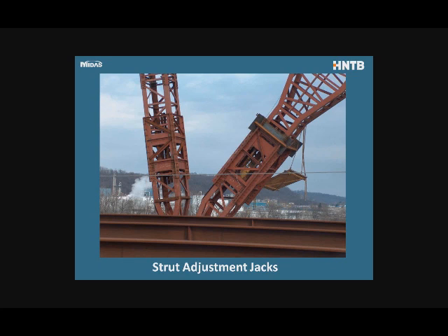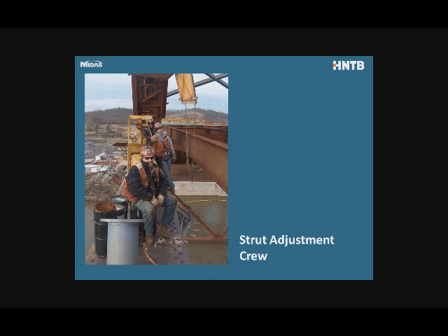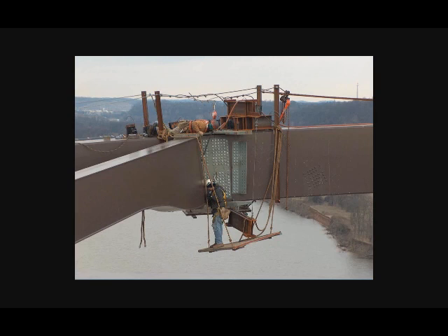And so just by inflating and deflating the jack and adjusting the nuts on the rods, they could adjust the jacks to, again, a fraction of an inch, 1/8 of an inch, no problem. And here's your friendly strut adjustment group. It's 3 people. The guy in front runs the hydraulic pump, and the 2 guys in the background adjust the nuts.